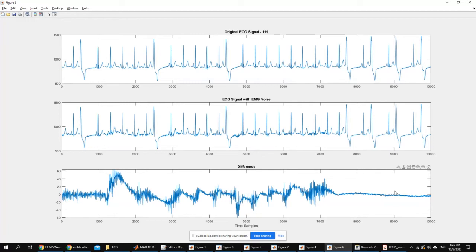Once you do that, this is step number one. Step number two is to implement the right filter for what you thought. So for example, if I have something that has variations that look like this, would you consider these variations to be low frequency or high frequency? The baseline variations here, will they be high frequency or low frequency? You see what I'm talking about? Such variations, not the very small variations here. No, I'm talking about the global variations like these. Are these high frequency or low frequency? I'm talking about low frequency or high frequency compared to ECG at least.